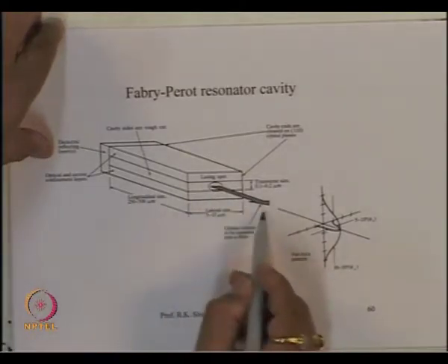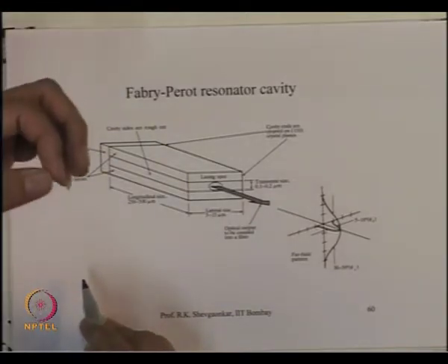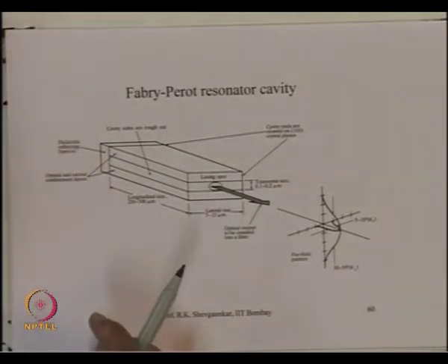So, I can use this mechanism to find whether my laser diode has gone into switching action, into lasing action. Let us say I take a laser diode and slowly increase the current inside the laser diode and keep looking at it at an angle. Before the threshold, since the laser diode works more like an LED, the light comes over a very wide angle. So, you can see the light very dim, but you can see it from a tilted angle.